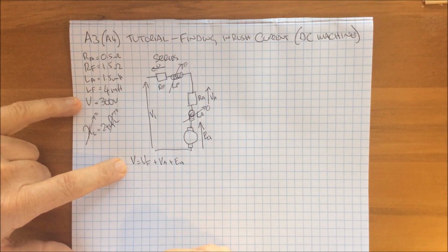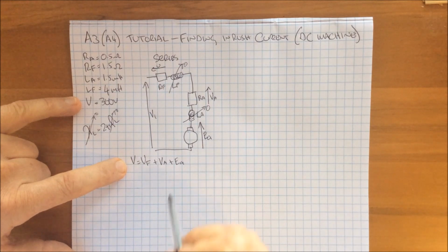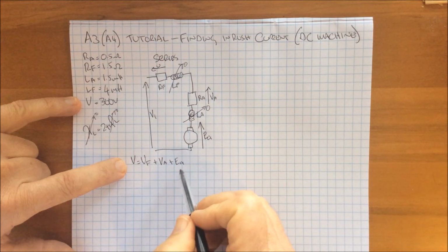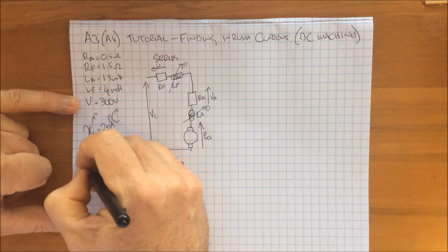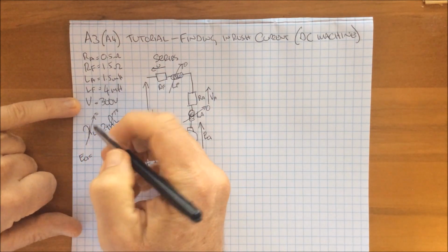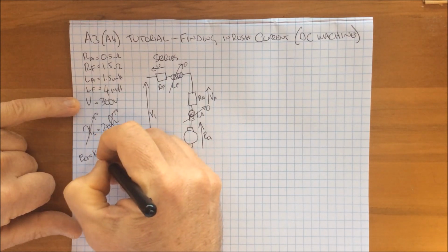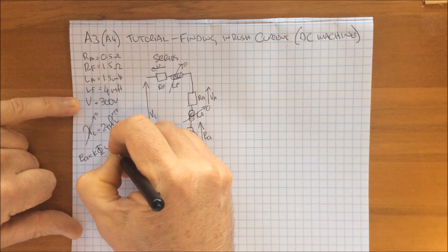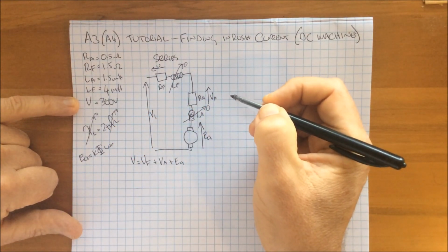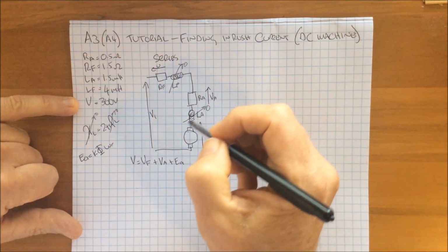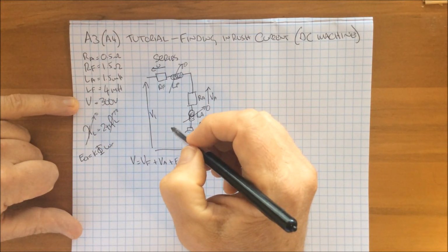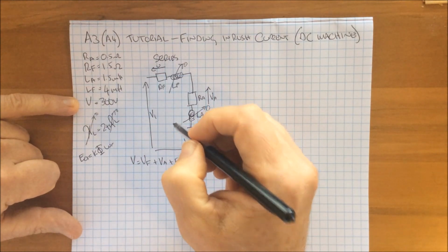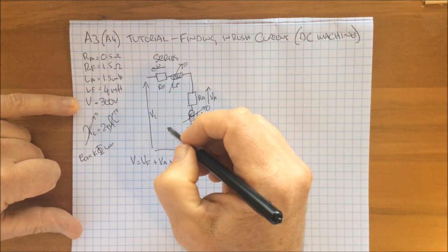Now, we also know that the back EMF generated in the machine is the machine constant times the flux times the speed in radians per second. When we first turn the machine on, and its first inrush current, the machine is going at 0 RPM.